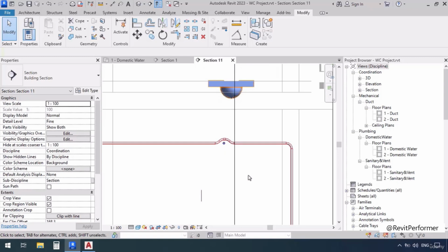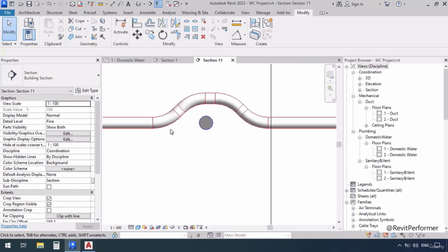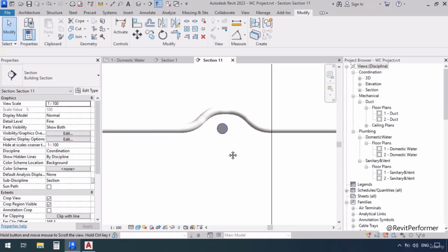The cold and hot water pipes are usually drawn parallel to one another, and they would be installed at the same elevations. Also, like I said, they could just bend the pipes when they're installing them. But when we are in Revit, we're going to have to model them with 4 extra elbows. But what's the result of this? While quantity surveying, it's going to show us 4 extra elbows, whereas we might not even need any.